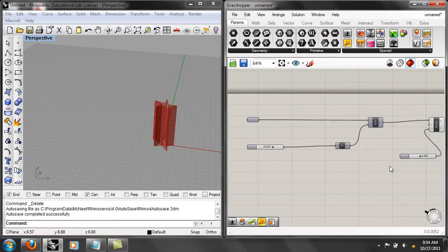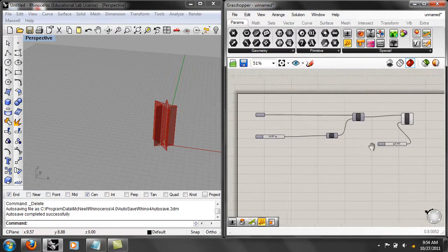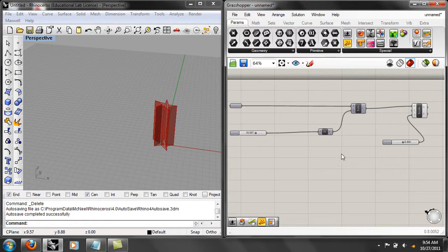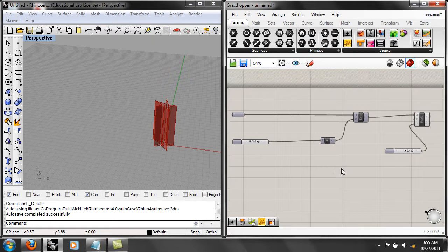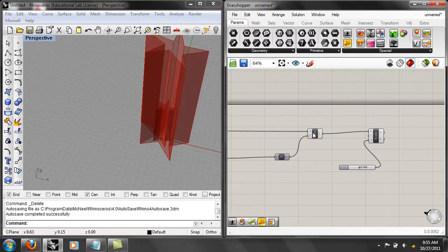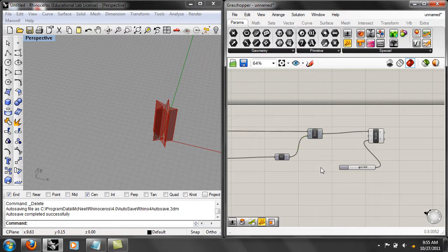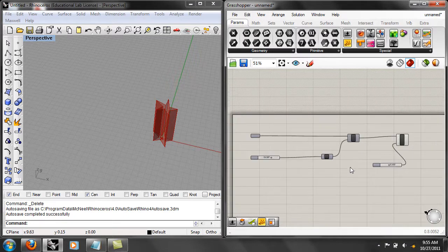And I told you about zooming and panning. To zoom, you just use the mouse wheel, and pan is the right mouse button. Why do I see both of them together? Because you didn't change the preview. You'll see two things because you have to turn off the preview of one of them. Otherwise, you see everything. You're going to have to get used to that. Any more questions about that? We all set?